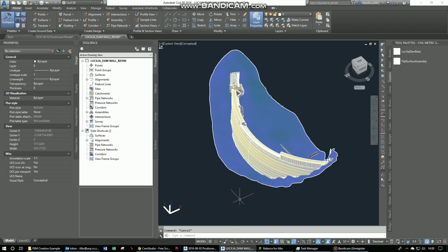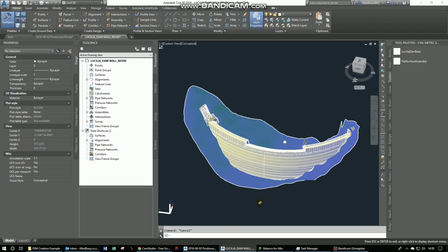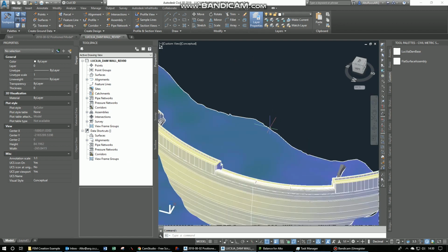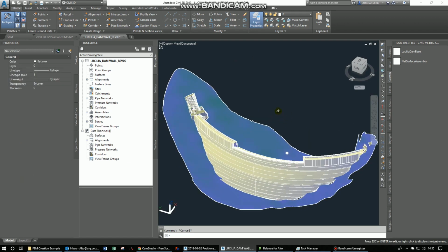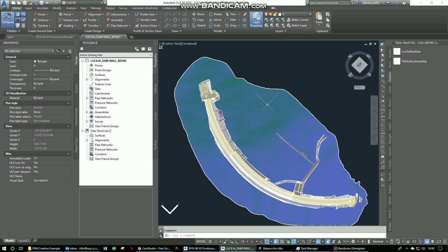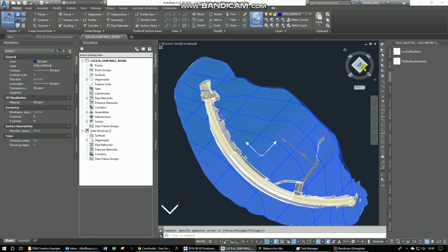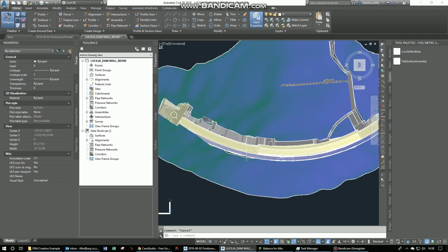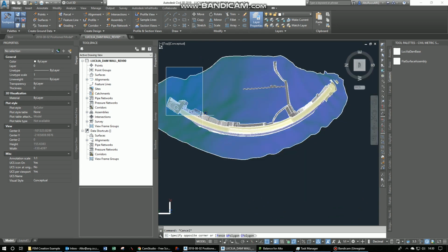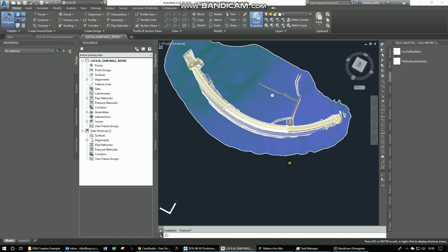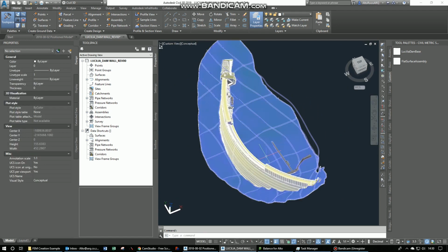Okay, this is going to be an example of creating a model that'll be used in FEM calculations in a different software package using Civil3D. We will take some sort of survey input. Also, we'll be combining surfaces in Civil3D as well, then converting the relatively fine mesh created by Civil3D surfaces into something better suited for FEM software.